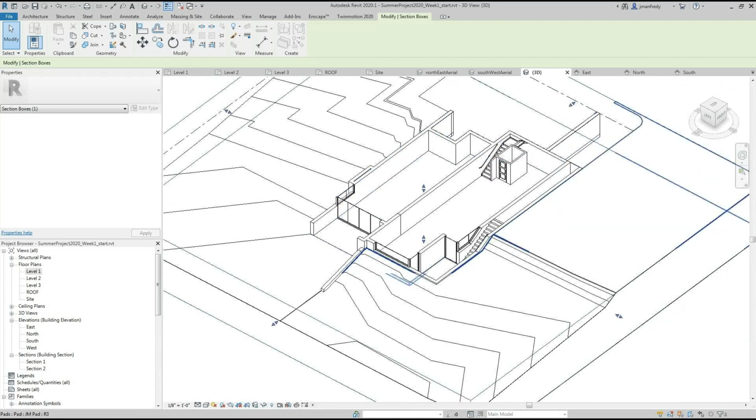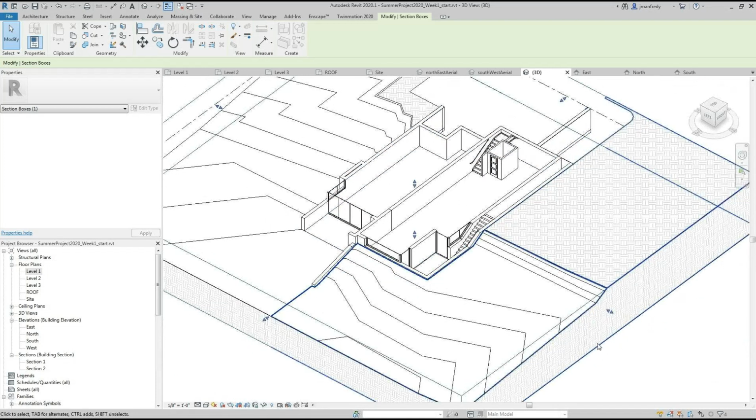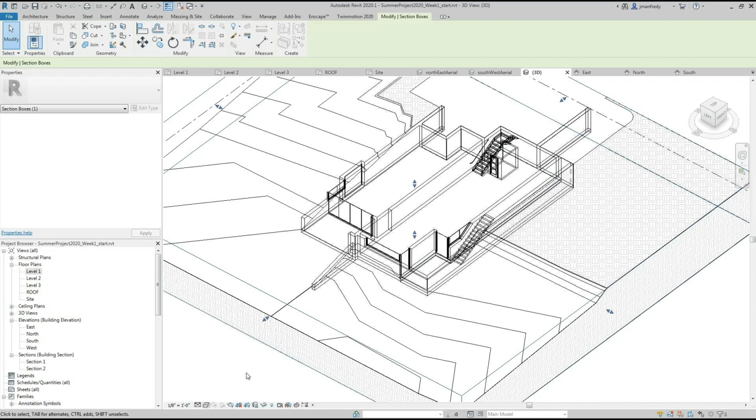In this view here, I'm going to go to this box here, and these are all my visual styles, and you might be familiar with this from AutoCAD or SketchUp. All programs do the same thing. They let you change the look and feel of the drawing. I'm going to choose hidden line, and that's what I'm in right now. Nothing happens. If I choose wireframe, everything goes transparent. There. If I choose shaded, everything defaults to its shaded color.